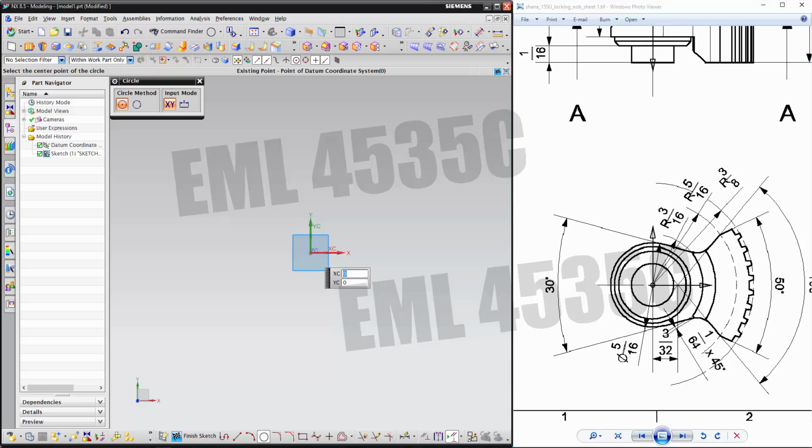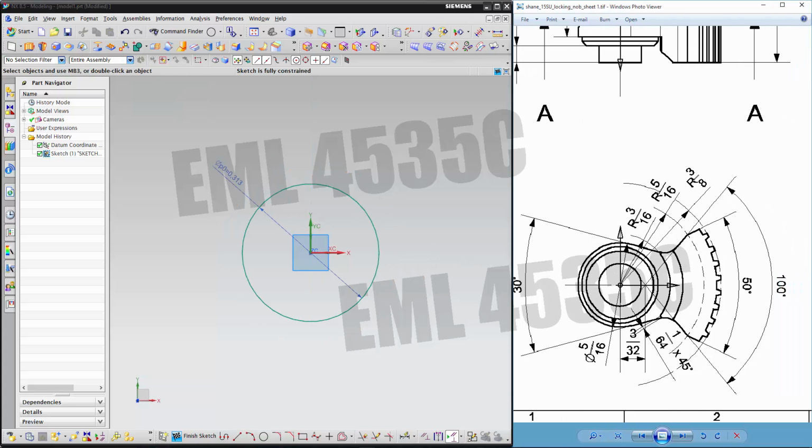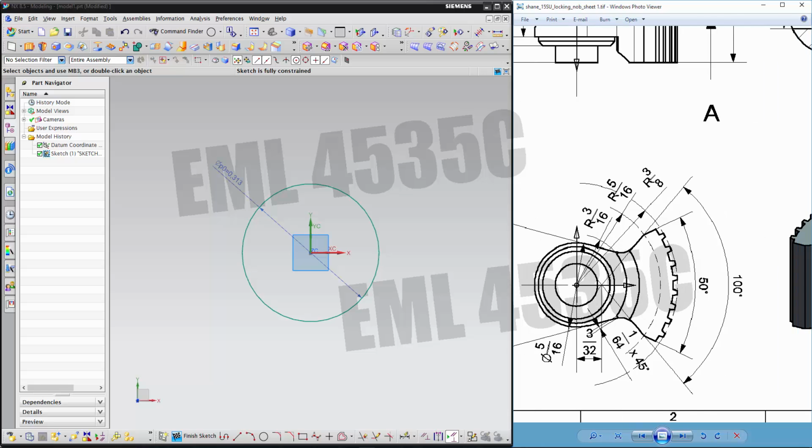Then we'll start from the circle in the middle, the biggest circle, which is diameter 5/16. So 5 divided by 16. Then it comes tangent to 2 lines, tangent into where? Let's see where. Well, we can start from the rightmost circle, which is radius 3/8.